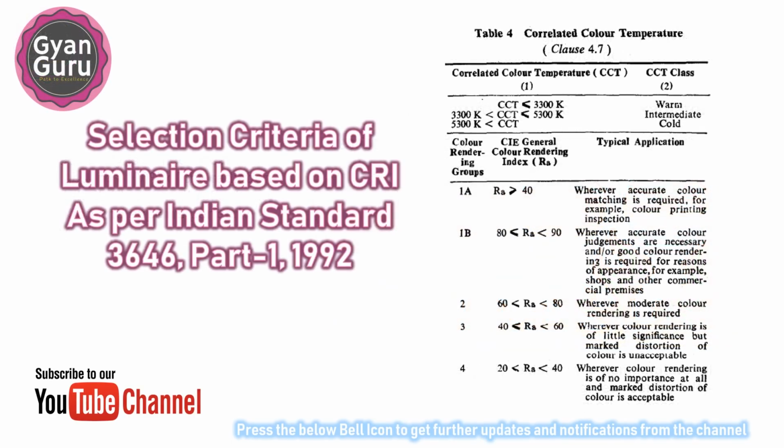Selection criteria of luminaire based on CRI as per Indian Standard 3646, Part 2, Table 4. Here in the table you can see the recommended value of color rendering index for the category of warm, intermediate and cold fixtures. Application of color rendering between 20 to 40 is wherever rendering is of no importance at all and marked distortion of color is acceptable.